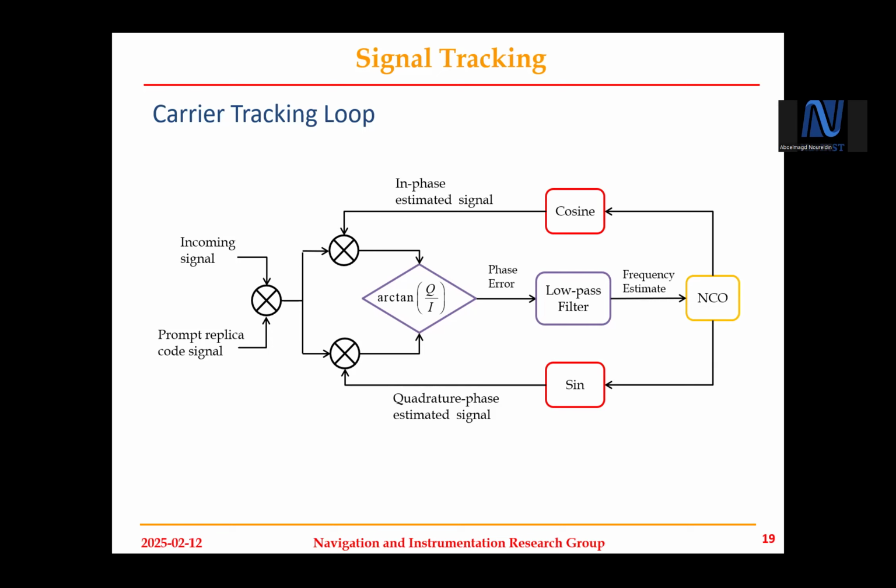I have two terms now, one scaled by the cosine of the difference, and this difference is very small because my estimated frequency or phase is close to the incoming one. So that will be the cosine of nearly zero. We consider that one. How can we exclude, or get rid of, the other term which has the sum of the two angles?